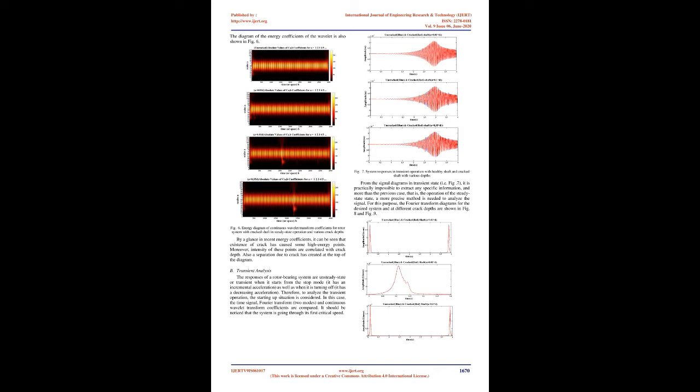On the left, the element containing the crack is element 12, and for the steady-state operation mode with rotational speed ω0 equals 80 rad/s, and for the primary angular acceleration equal to 30 rad/s², the Houbolt method is used. For more information on this numerical method and other available numerical methods for solving multiple equations, see reference 18.